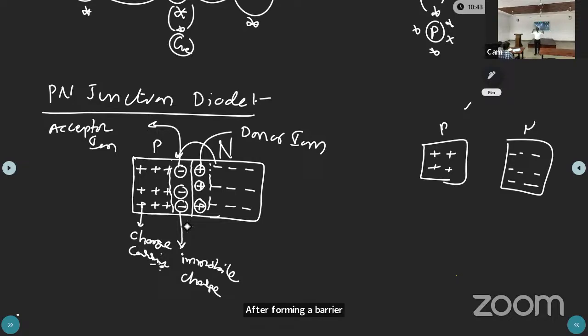Here we are not applying any electric field or voltage to the PN junction. Simply, we take one crystal bar, add p-type semiconductor on one side and n-type semiconductor on the other side. Because of this joining, some electrons are shared with the p-type semiconductor, and immobile charge carriers form: donor ions on this side and acceptor ions on this side, between the n and p-type.